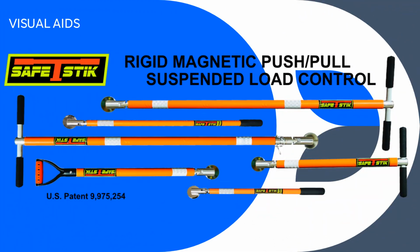If there is a suspended load, how can we control it? We all know we use a tag line, but when the load is low, it means it's not going to a great height, maybe 2 meters or 1 meter from the ground, we can control it by hand. But this type of tool, a suspended load control tool, we call a magnetic grab tool. You see this magnetic part, it will hold or grab the plate or some suspended load or material. We can grab from here and hold from here. This extension may be 1 meter; it is available in different sizes, 1 meter, 2 meter or 0.5 meter.